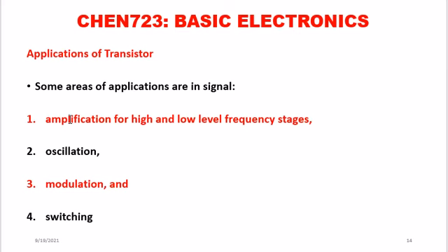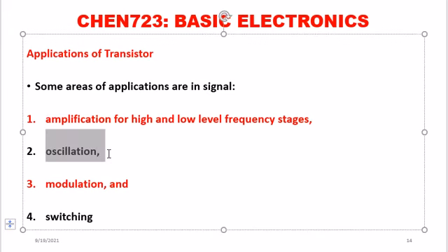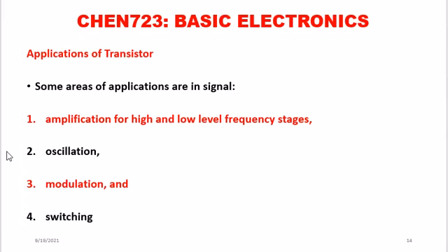And then there is an oscillator. The oscillator is something that will take a DC input and produce what? An output as an AC. For instance, all the sirens on the vehicles of our governors and what have you, the police, fire service, they are all made using oscillators, and these ones are called audio oscillators because we can hear them. We have radio or modulate oscillators, which have a very high frequency beyond our hearing.